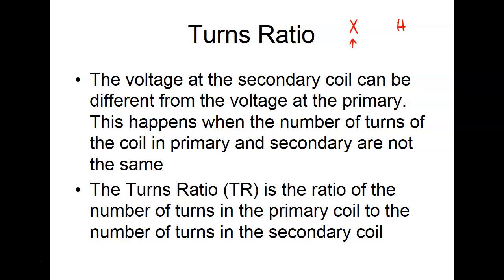So if I wanted to step down, I would bring my voltage in on the high voltage and take it off the low voltage. If I wanted to step it up, I would go backwards, right? Everybody okay? So this is standard in industry. The low voltage terminals are going to be labeled with X, and your high voltage is going to be labeled H's. And we'll see that on our transformer.